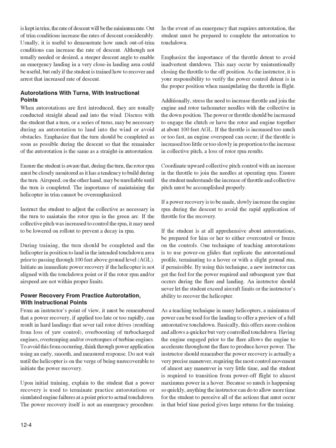By using this technique, a new instructor can get the feel for the power required and subsequent yaw that occurs during the flare and landing. An instructor should never let the student exceed aircraft limits or the instructor's ability to recover the helicopter.